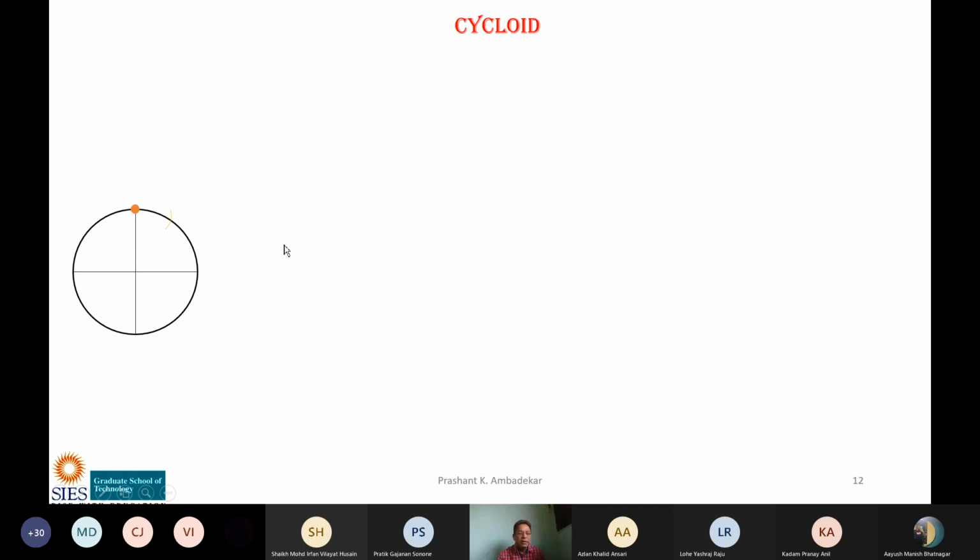See now, repeat this. See this arc and draw a line. Then again arc and draw a line. Then again arc and draw a line. Then keep the compass again, arc and draw a line. Is the procedure to divide the circle into 12 parts clear to all of you? Yes, sir, clear.